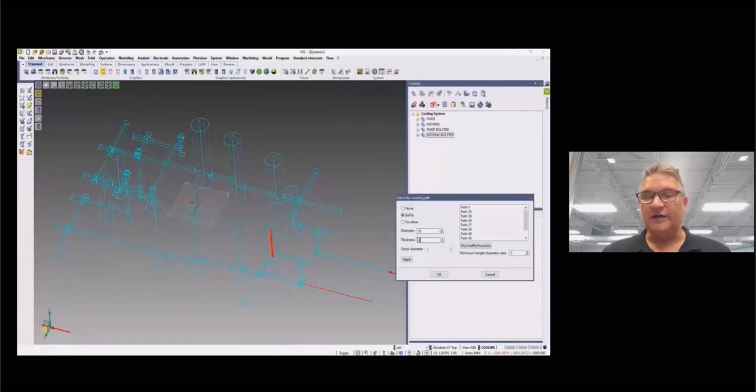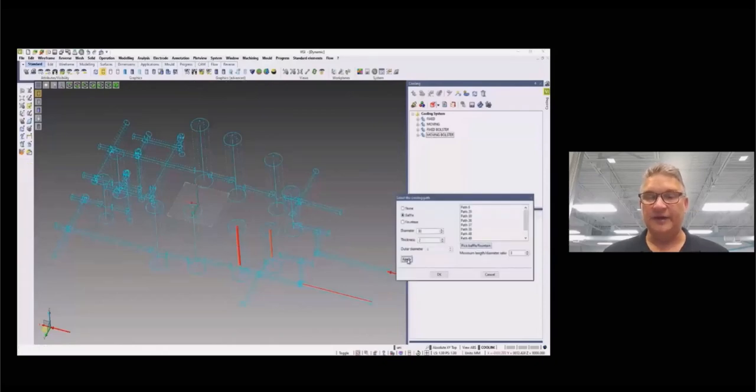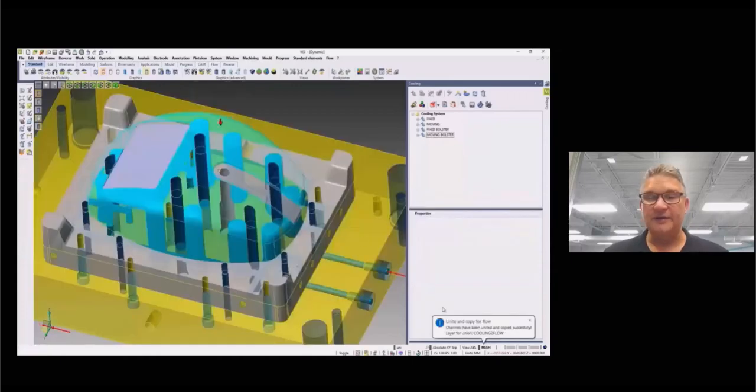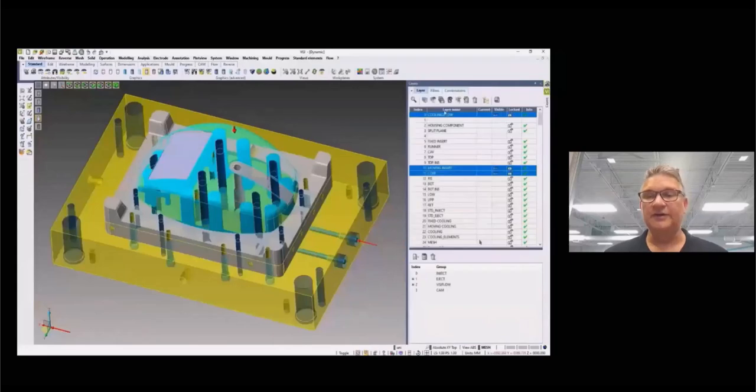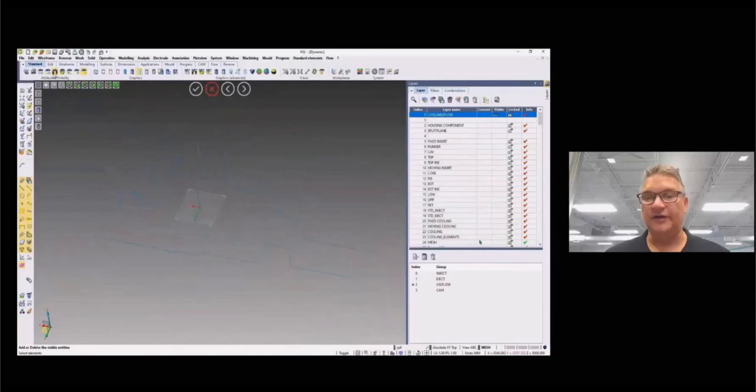You can always define the baffles as shown here. Just select from the list and add the parameters. Then pick the next baffle until they're all updated. Once done, a message will confirm that it was copied and ready for the flow analysis. For example, in this case, we passed all this information, including the baffle information, into the flow analysis module.